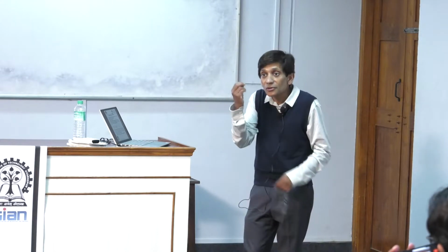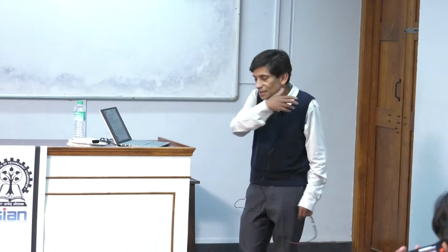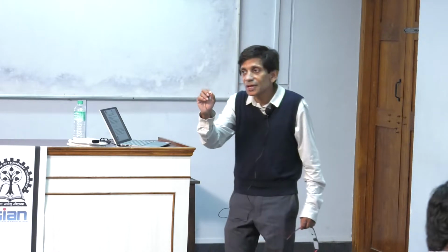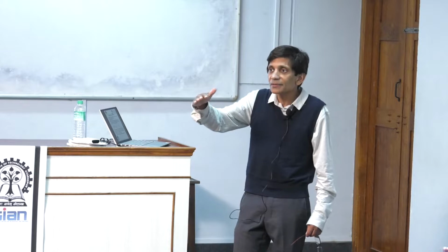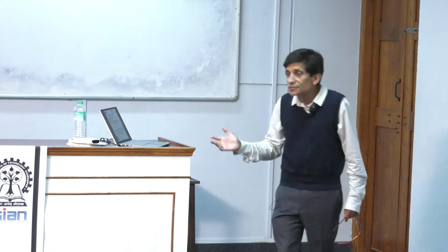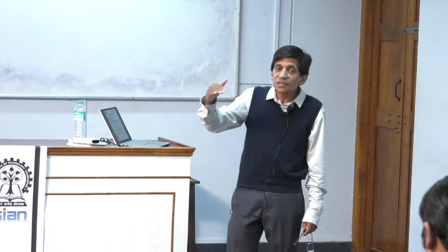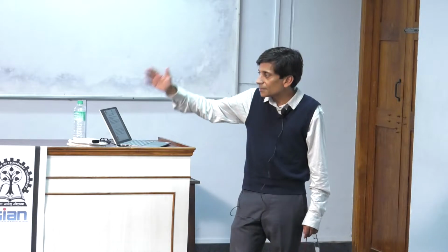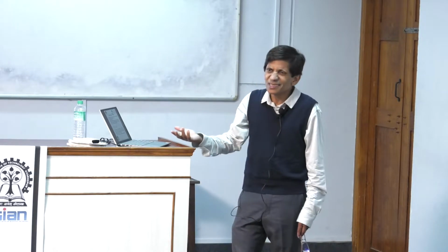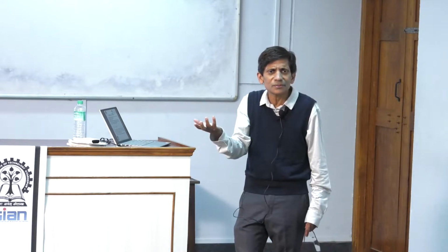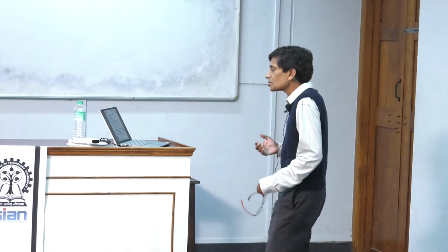So this is a volumetric flux. You can have a mass flux. You can have many sorts of fluxes, right? But the flux is whatever is being transported divided by the area by time. So if it's per time, that's obvious. That gives you a rate, right? But the reason we divide by area is then we can compare different membranes. So with membrane A, B, C, which is better? It's hard to say. If you just did flow rate and the surface area was different, how can you compare them? So it's per area. So that's why we talk about flux.